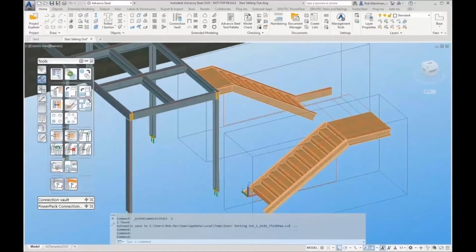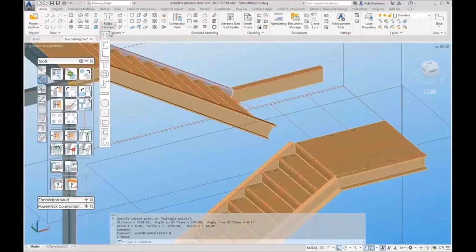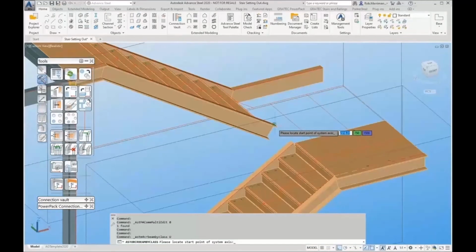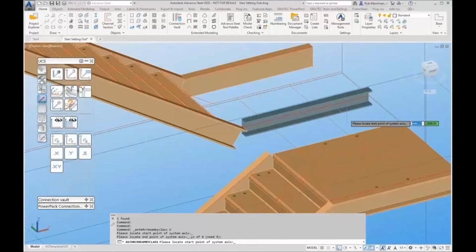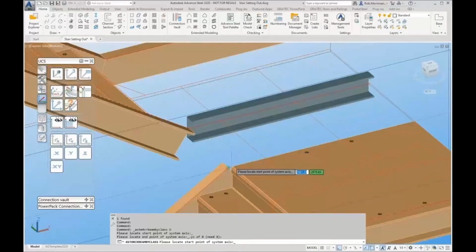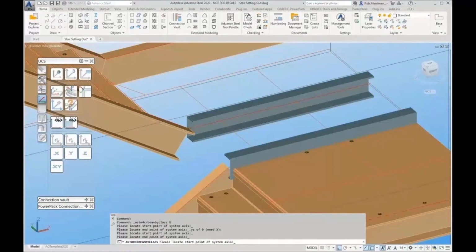So now we need to draw in our various cross beams. So I'm going to go from the bottom of here with just a channel, bottom of that stringer, and I want to go forwards to line up with the end of the other stringer. So I can use the point filters, I only want to go in the X direction, so I click on .x, and then I can snap to the end point, get 0 in the X and Y, snap to the end point of that beam, and it just goes the matching length. Do the same from these, so I want to track across from that one to get the end point of that, like so, and then draw it this way so I get the toes going the right way.